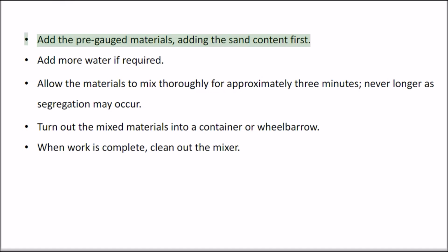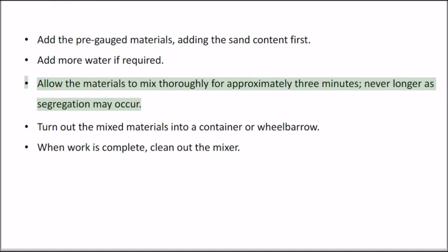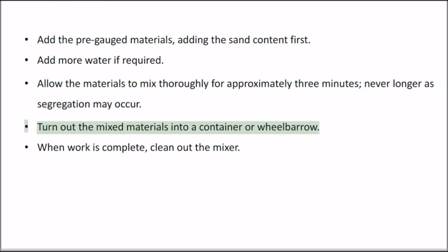Add the pre-gauged materials, adding the sand content first. Add more water if required. Allow the materials to mix thoroughly for approximately 3 minutes. Never longer, as segregation may occur. Turn out the mixed materials into a container or wheelbarrow. When work is complete, clean out the mixer.